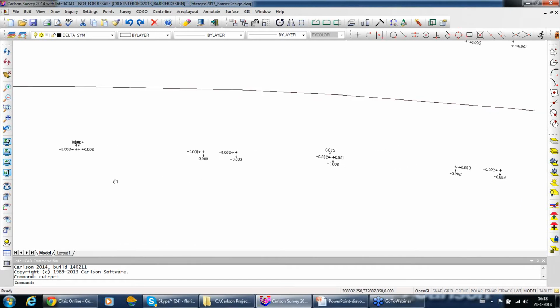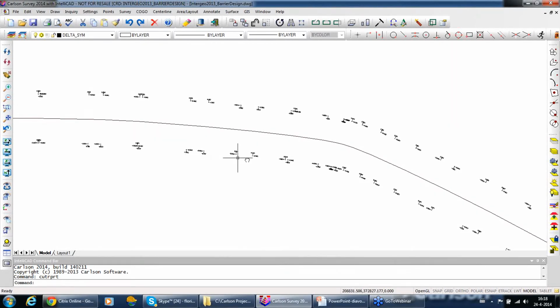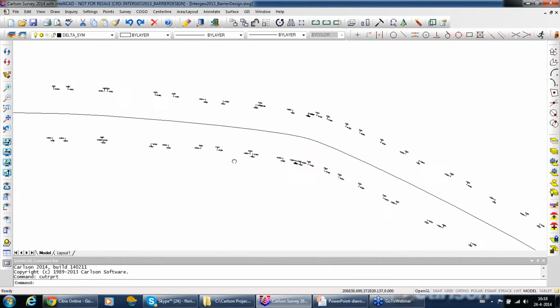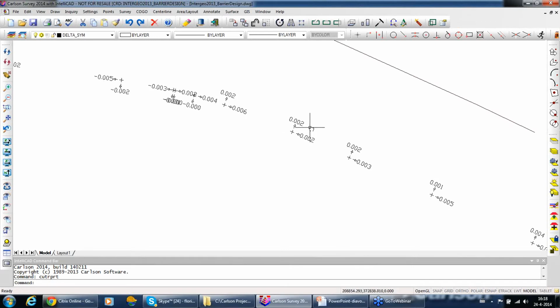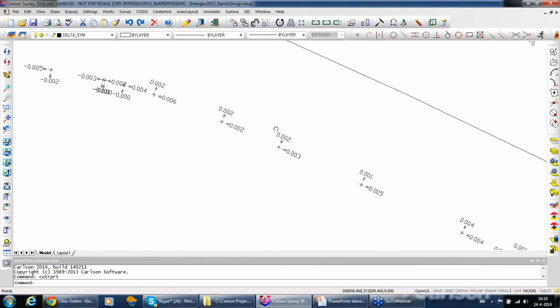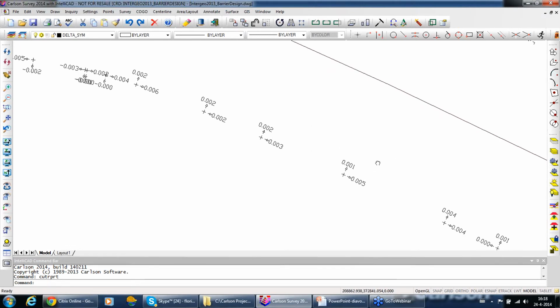So this is a better way of getting a feeling behind the numbers, because if you just plot values in a big table, you don't have any feeling with the values. But of course, in this way you can quickly see if they all have the deviations to the same side, or you can quickly determine what the cause is. Maybe with heavy machinery they drove too close to the stake, so then usually you would see them all going to the same direction.